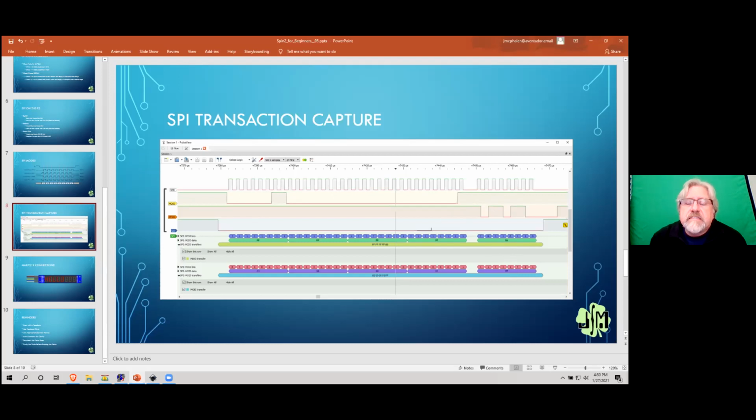It's very, very easy. Now, you can have devices that will send data master to slave and at the same time get data back in. It's not very common, but one of the clicks that we have, that I've got to finish up some code for, is called a MCP2515, which is an interface for CAN bus, and it sends and receives data simultaneously. That's where the 2 pins come into play. If you have a device that is going to send and receive at the same time, you have to have 2 pins. Okay. Any questions?